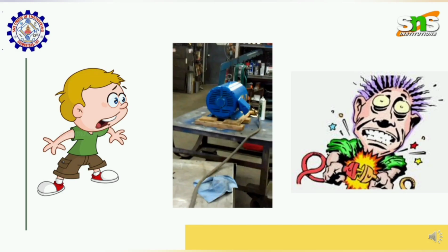Generally, in a manufacturing facility, an induction motor failure was observed due to a combination of factors. The motor had been in service for several years without routine maintenance, leading to the accumulation of dirt and debris, especially in the air vents and around the motor windings. Additionally, there were signs of overheating, likely caused by poor ventilation and inadequate cooling.